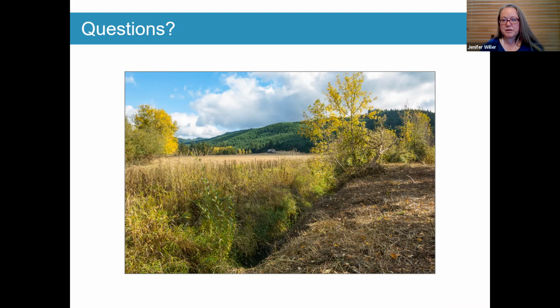Is the existing bridge superstructures being removed and replaced higher on the existing piles? Yeah, so the existing bridge superstructures will be removed as part of this project because the county is raising the road up and they're going to build a new superstructure across these. So I'm sure that that would facilitate the placement of the riprap, which is pretty tight under there.